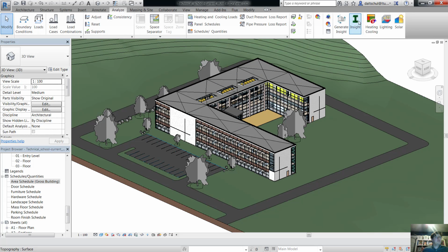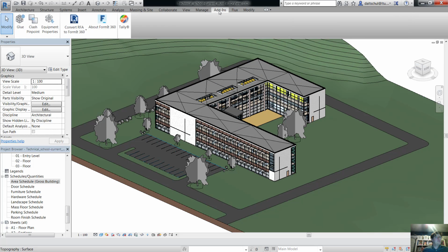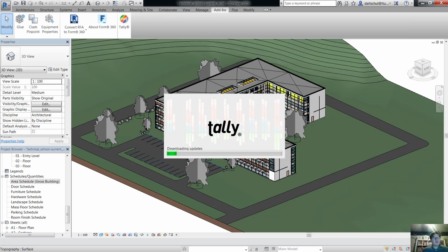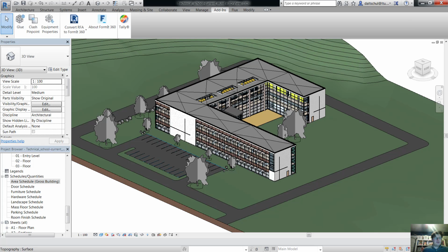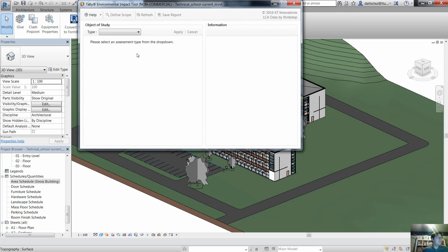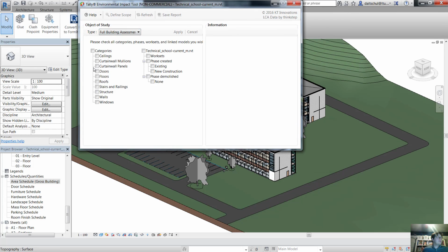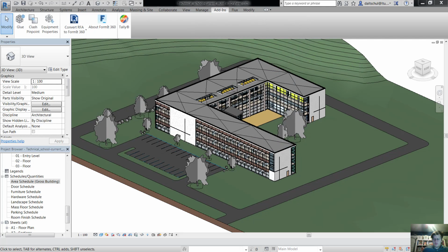And when you create the LCA, just remember when you're changing between the finishes and your components, you want to be sure to only have the appropriate category chosen, or else it will produce an LCA that has a mixed finish in doors, which is okay. We might want that in the future. So, all right, so there's part 1 of the assignment.